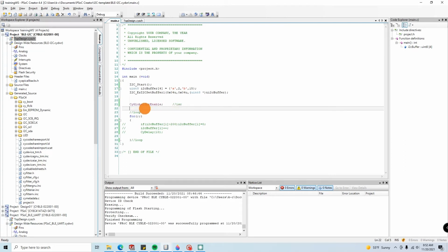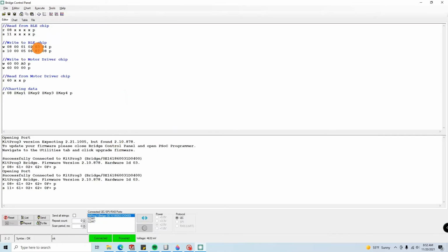You can do it line by line, and you might have to use the full address, declaring that last bit. Where when you do the one command that's something like master read buff, that read, so it knows. So that means that you'll be using the 7-bit address. So that read function, it'll set the last bit for you. Anyways, so write to the BLE chip.